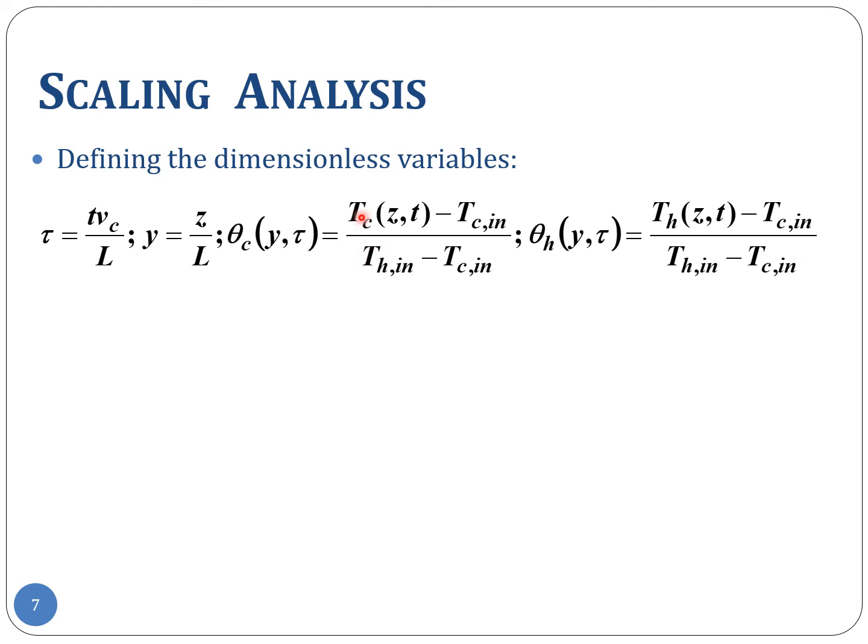To define a dimensionless temperature, one needs a characteristic temperature. Just as you have a characteristic length, you take the absolute length and divide by the characteristic length, you get a dimensionless length. So if you take an absolute temperature, divide by a characteristic temperature, you will get a dimensionless temperature. But I have defined a dimensionless temperature difference here. Therefore, I need a characteristic temperature difference, which should go in the denominator.